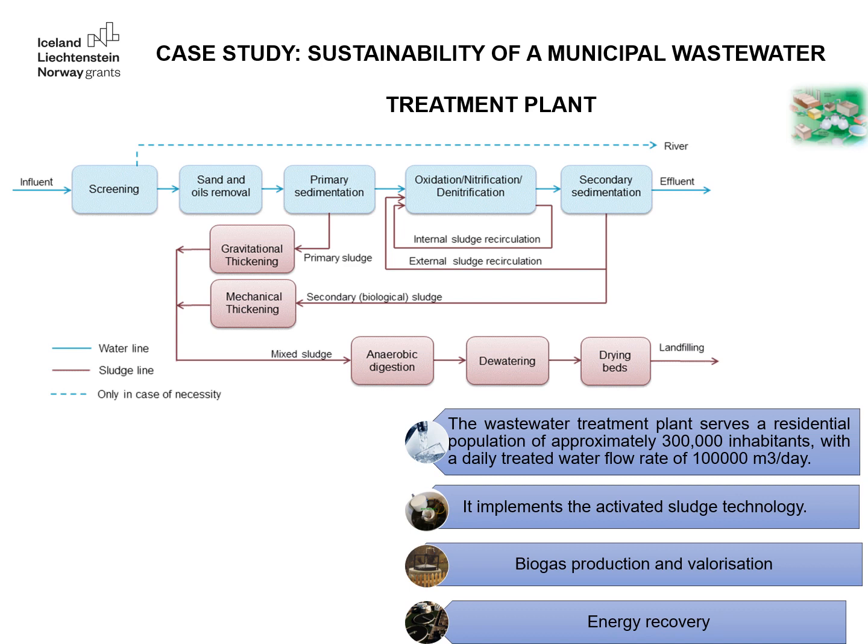Secondary sedimentation. The treated water is then directed to a secondary sedimentation basin where fine particles and flocs resulting from the treatment process are separated. Anaerobic digestion of sludge. The resulting sludge is transformed through anaerobic digestion into biogas.